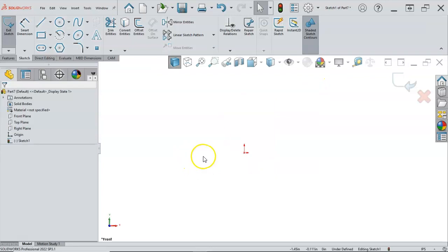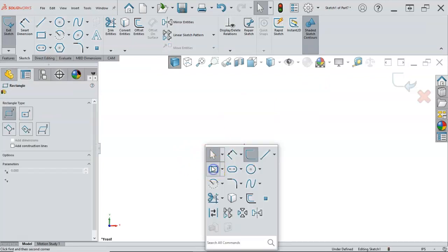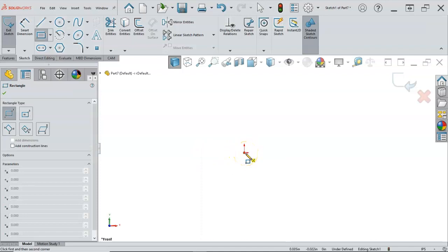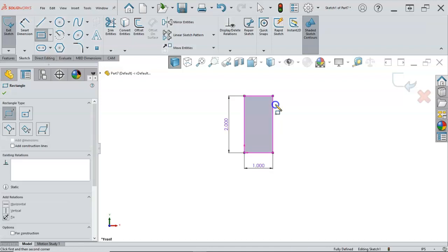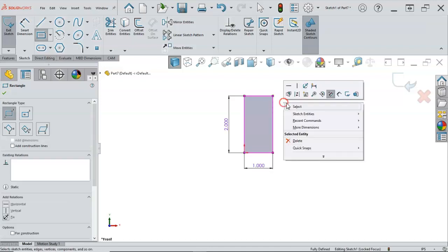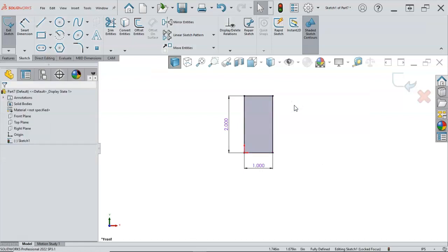All right, and then the last one, back to the S key. Again, pick your favorite one. I try to do all three so that you see it, but hopefully it doesn't make it too confusing. So if I'm doing the click drag, then I need to keep holding down the mouse button, because if I let go, it's going to say, oh, you didn't put in a value, you don't get any dimensions. All right, so 2 and 1, and then it lets me out of the rectangle.